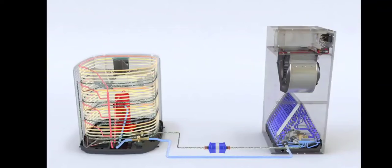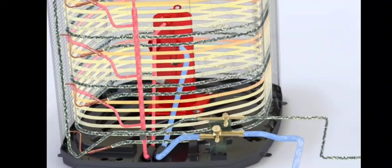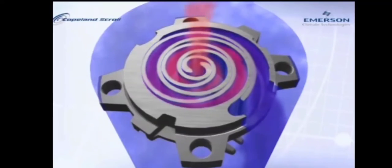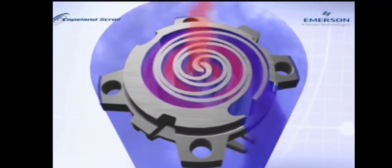Now this cool refrigerant is going to make it all the way back to the outdoor unit through that large insulated vapor line, sometimes referred to as the suction line. And the cool refrigerant reaches the outdoor unit and feeds back to the compressor, keeping that compressor nice and cool. The refrigerant is going to work its way back into the scroll plates again, and it's going to become compressed to run another cycle through the refrigerant system, keeping that homeowner nice and comfortable.